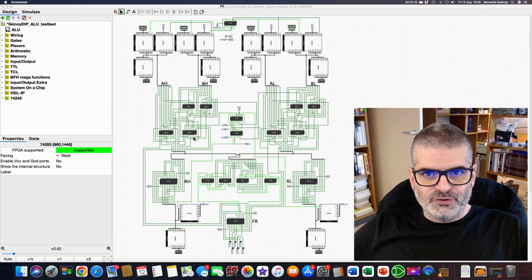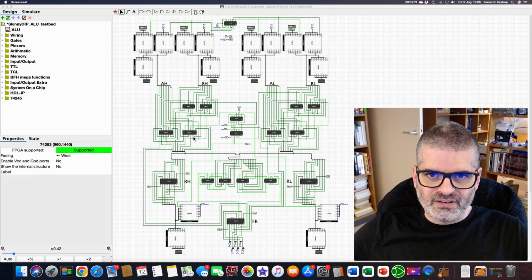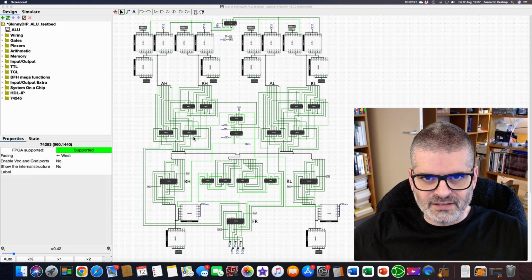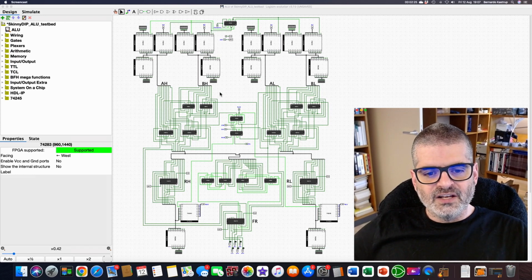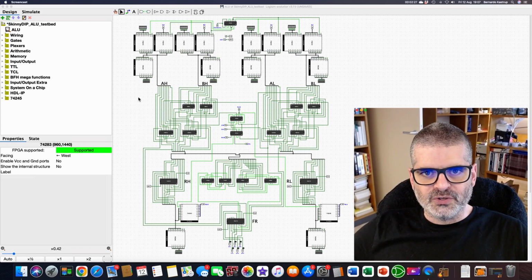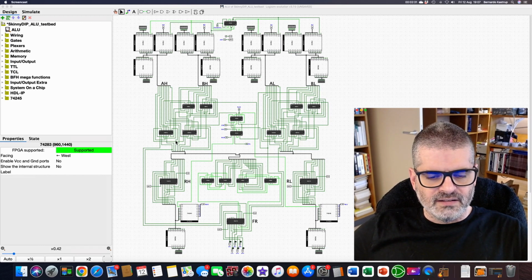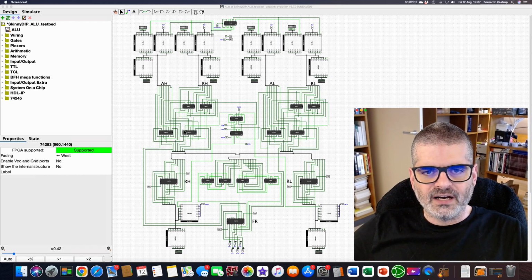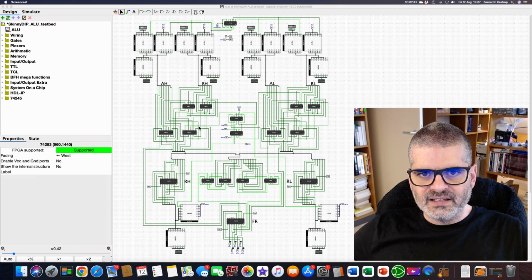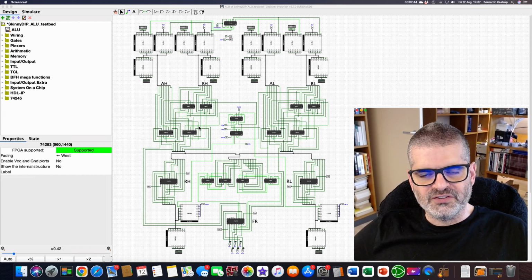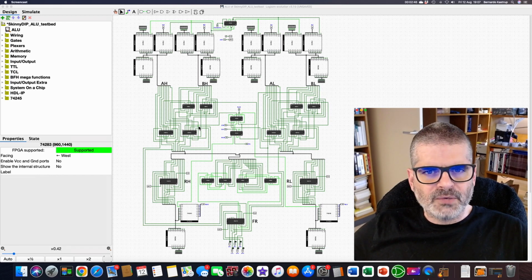Because what you see on a board are chips, not abstract floating individual gates. So I want to capture in the simulation the error-prone process of defining the netlist, defining how pins connect to pins. And if the simulation runs correctly, then I will know that I connected everything correctly, and then I just move the netlist over to a CAD tool for PCB design without having to think about the functionality again.